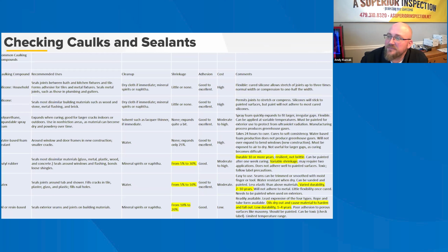With proper adherence to the manufacturer's installation instructions, particularly with respect to surface preparation, high-quality caulks and sealants can be made to endure for a reasonable length of time between maintenance and replacement, up to 5 years, or considerably longer when not severely exposed. Silicone rubber and urethane caulks generally give the best overall performance for applications to exterior building envelopes. For bath and shower applications, mildew-resistant silicone caulk is also available.